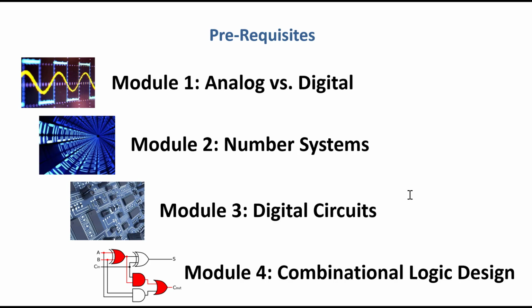And we also needed to look at the interfacing between gates. So if one gate is going to produce a logic 1 and it's represented as a certain voltage level, the gate that receives that information has to be able to interpret that voltage level as the logic 1. So we needed to be able to design circuits that can interface with each other, and we needed to be able to understand the operation of these gates in order to interface them properly. So we needed to look at their data sheets. We looked through their data sheets and we looked at a whole bunch of characteristics about these parts, and we also looked at both DC characteristics but also the AC characteristics, so how fast they switch.